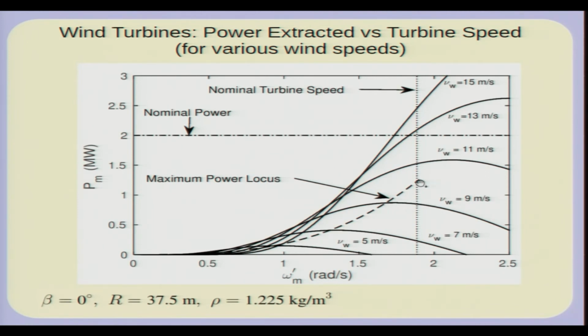If your speed goes beyond the rated speed, after that you need to shift over to speed regulation. So, you have to control the machine so your speed is regulated, and in trying to maintain the speed, if the wind speed increases to a very large amount, then the power output of the generator may increase beyond its rated capacity. If that happens, you better start reducing the power of the wind itself, and that can be done mechanically by changing the pitch angle, or the rotation of the blade on the longitudinal axis.